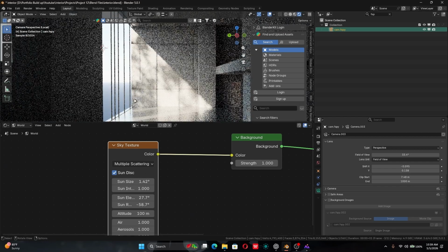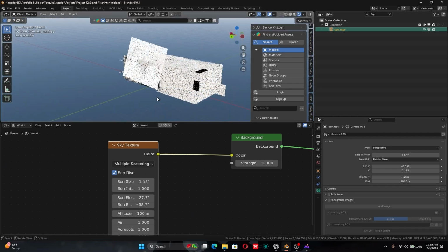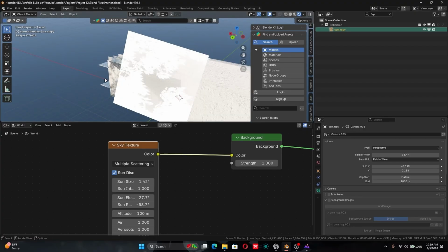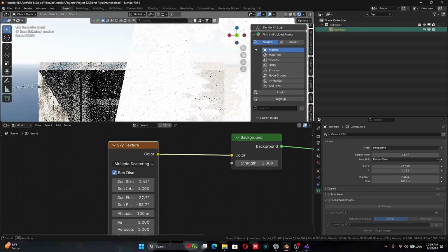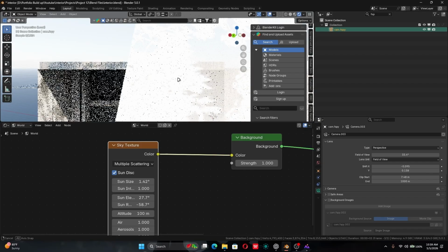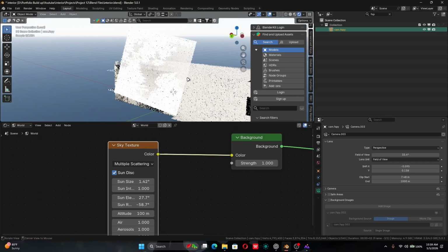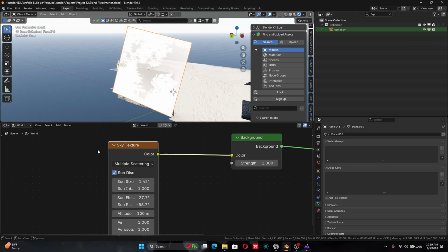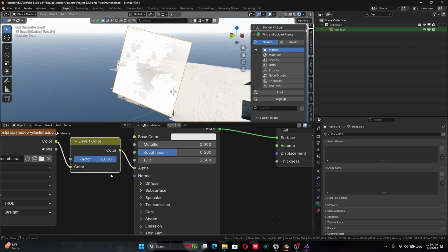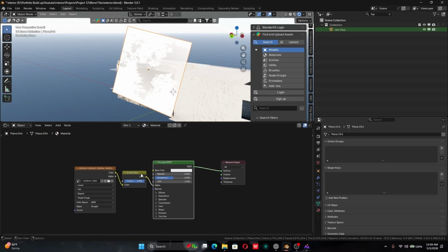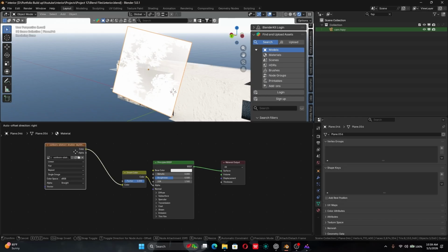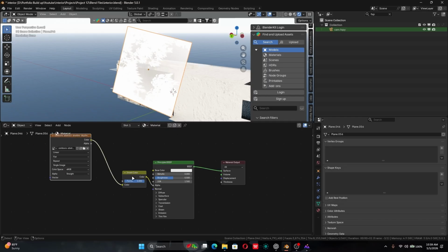Now for the gobo, I explained that it's just to cast shadow to the scene. So instead of having high poly trees that are casting shadow to the subjects, you can just have a simple plane, have a pattern that we want to cast, and it's going to do that. So for the material of this one, if you go to objects, you see it's just a normal principled BSDF. You connect your image texture to an invert color depending on the type of texture you are working with.